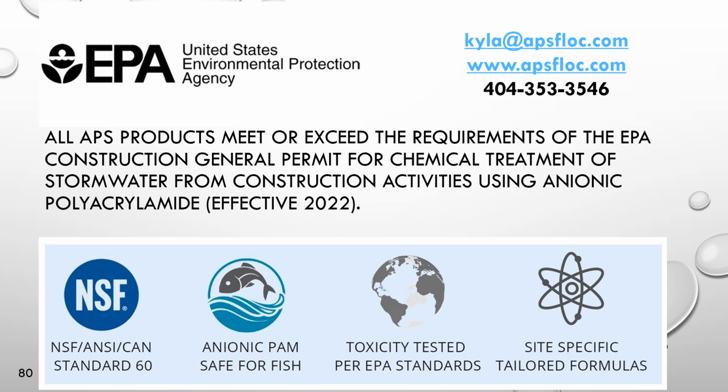erosion control. What we want to make sure we're doing is all of the polymers that we've talked about in the last 3 hours are NSF Standard 60 certified, meaning that these polymers meet drinking water standards. All of the polymers that you use for erosion control and stormwater should meet drinking water standards just in terms of safety and quality. Most states and EPA guidelines require that.